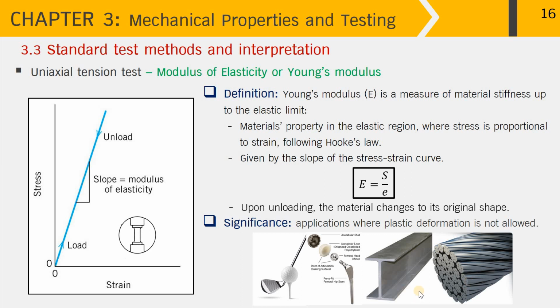You can't take a chance that yielding will occur in service, so you need this steel wire rope or steel bar to behave in an elastic manner only, so you don't get any deflections in the whole structure. Imagine that, how safe it is. Imagine that if you are a civil engineer, you have to select the metal, and these parameters you have to consider for structural materials as well.